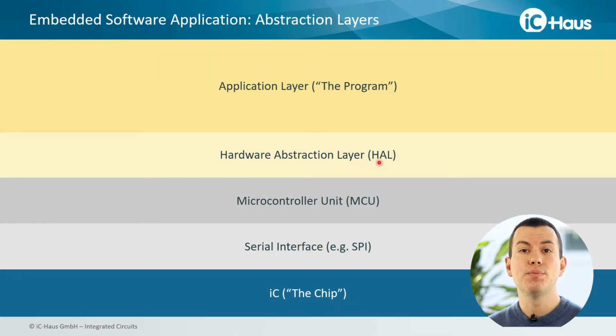The HAL basically provides well-readable, powerful functions to interact with a microcontroller on a somewhat higher level. So initializing an interface, controlling GPIOs, transmitting or receiving data, everything is done via one or just a few function calls, making programming so much easier for all of us. And this is basically the concept that we've been following with the MCU Drivers.